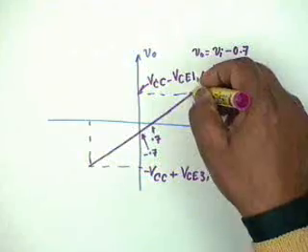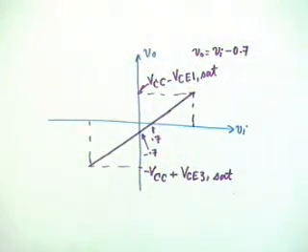You must be well within these limits. This figure only shows the limits, okay. You should not operate the transistor so that the peak swing goes here, because then you are asking for distortion. You could as well go to class AB or class B amplifier, okay. Class A amplifier is for low power level and very little distortion, okay.